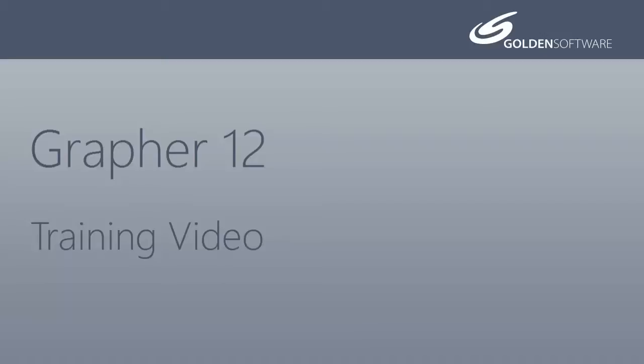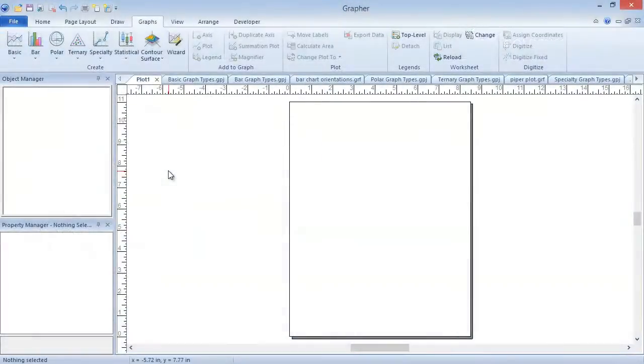Grapher is a powerful 2D and 3D graphing software package. In this video, I will briefly explain the different graph types available in Grapher. Grapher has over 70 types of plots that can be created depending on the type of data you have or how you want the data displayed. The types of plots are grouped into 7 categories: basic, bar, polar, ternary, specialty, statistical, and contour surface. These can be seen in the Create section of the Graph's Ribbon Bar tab.